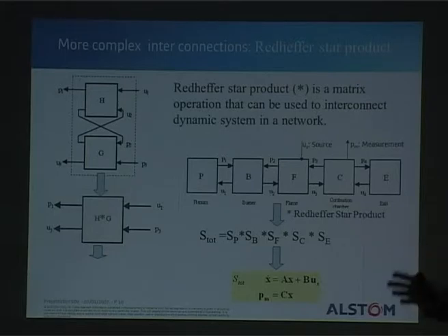If you had a loudspeaker and a test rig, then of course you would have somewhere here a thing that represents this loudspeaker, but in a gas turbine you don't have that. And then what you measure, the quantity you're interested in, for example pressures at different locations, or velocities, whatever you're interested in, you get that as a map of the state vector X via this matrix C. So it's a very generic, general description of expressing dynamic models.